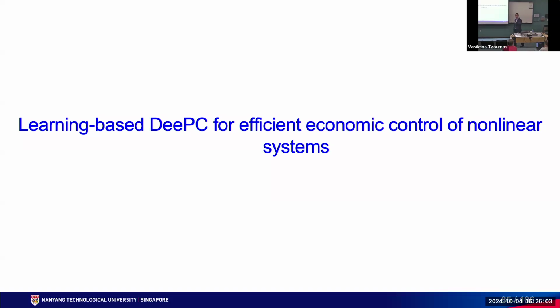Of course, when we recover the full state, we can use the estimation, but for offline modeling, we still need a full picture of all the system states. We need to collect offline data for all the state variables. We have no option. But, for example, in the case when even offline data collection may be a problem for certain states, we may probably prefer to use an input-output control framework. And this is something that can be addressed by DPC.